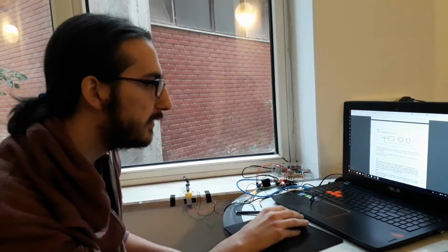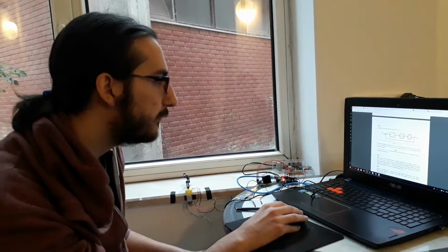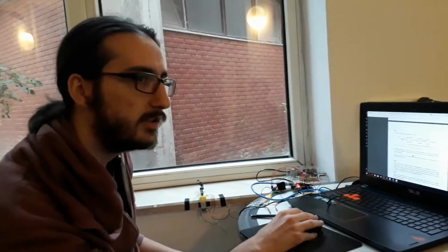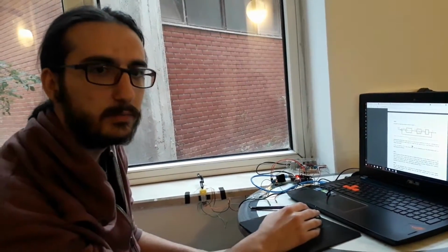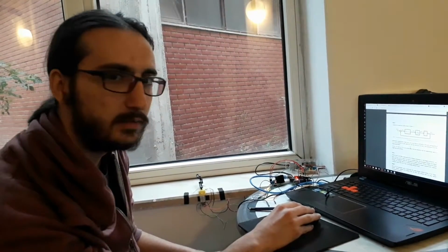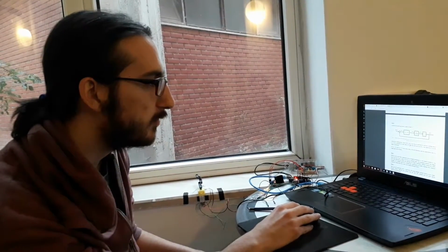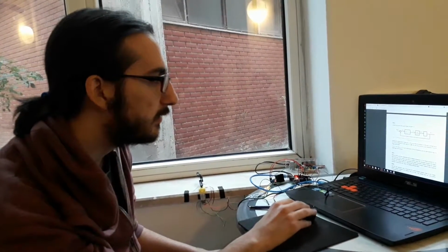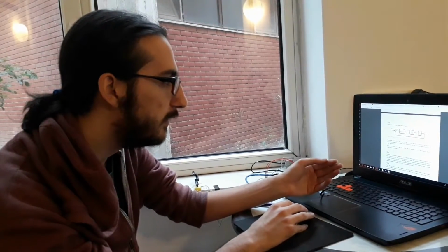First of all, we set a value for alpha, and then we rearranged the characteristic equation so that it is in the form of 1 plus alpha times T of S, where T of S is the open loop transfer function, and we plotted the root locus for this transfer function. And as I said before, we had given a value for alpha.